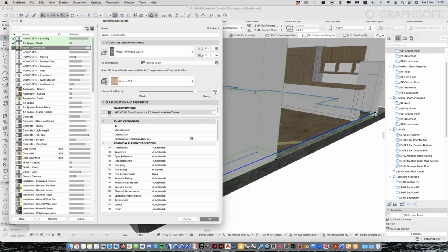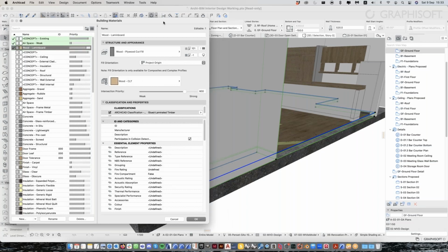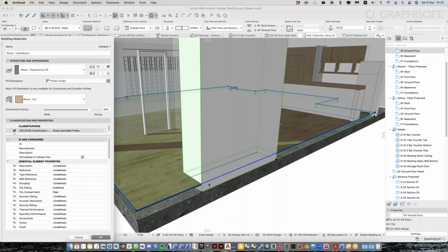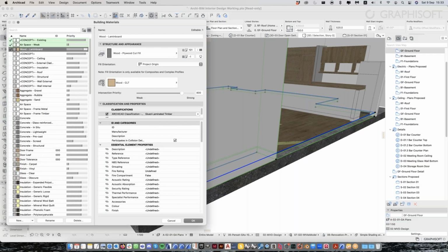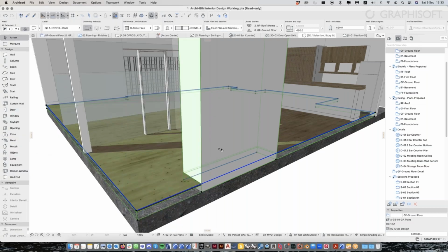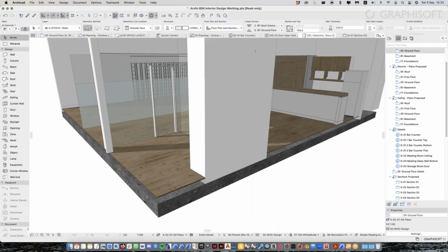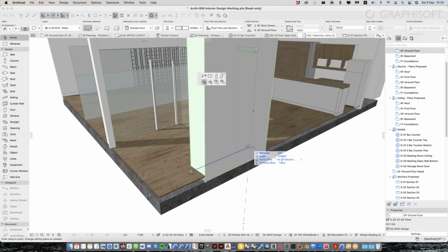So that's why, when they intersect, it's going to automatically remove itself from this intersection. So in that sense, you don't actually need to do a subtraction of this, like what I did. So when would this be handy, right? Well, maybe you realize once you went on site that this column is actually smaller, or it's a different size.